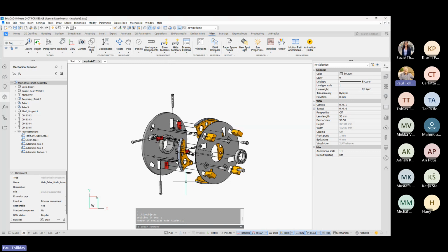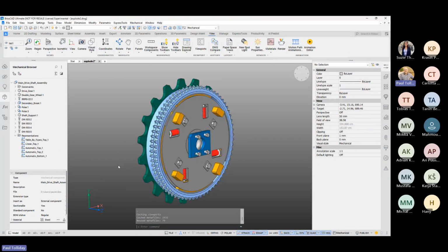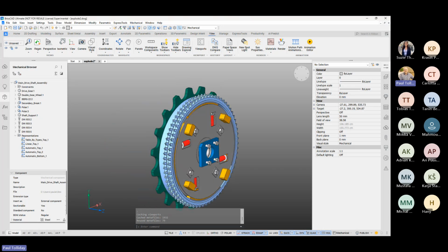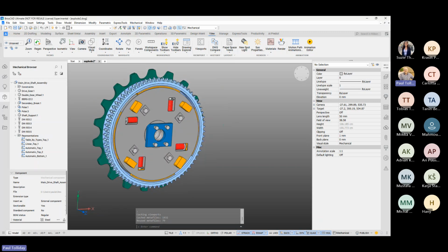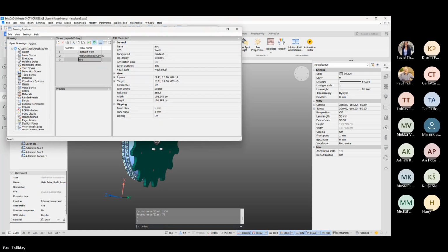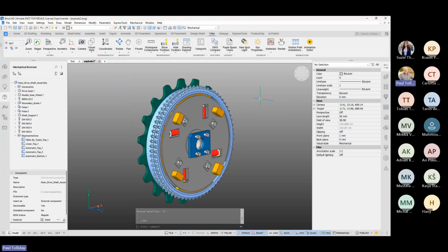And it also means we really must set that view so we can have the same view on top of another view. So there'd be nothing worse than if we come in here and we've accidentally knocked my 3D mouse. The chances of getting that view to be perfectly matched up again, it just wouldn't happen. So no matter where we are now, if we want that view back, we can simply go back to our views, click on the ISO 1, reorientates the model, and we've got the view exactly as we wanted it. So hopefully you can see the benefit of that.